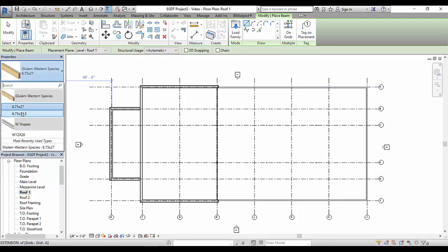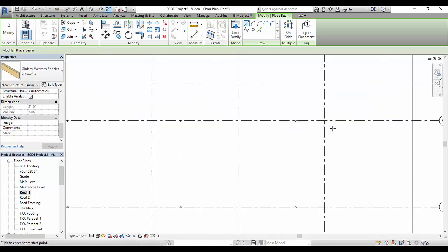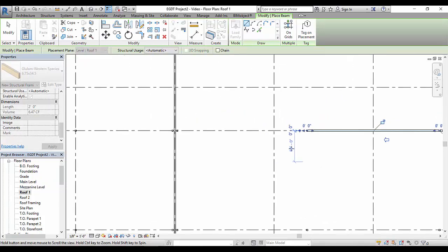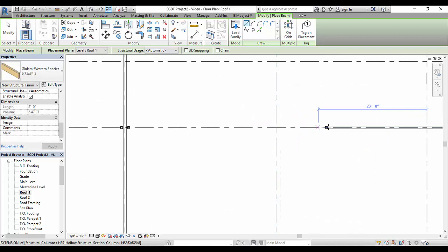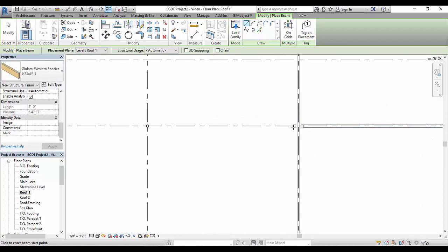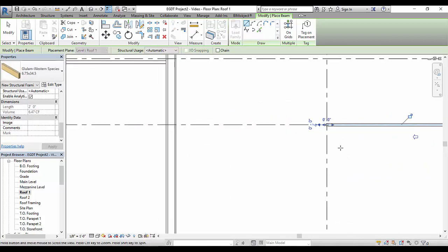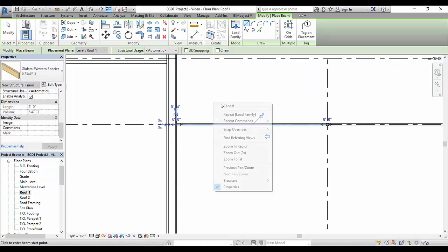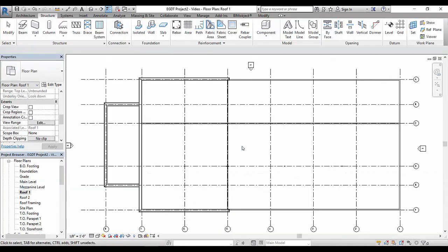I'm going to shift over to the 34.5-inch depth, and then I'm going to simply model these beams from the wall to the column, and then I'll go from column to column, down the one grid line and get those beams placed in there.